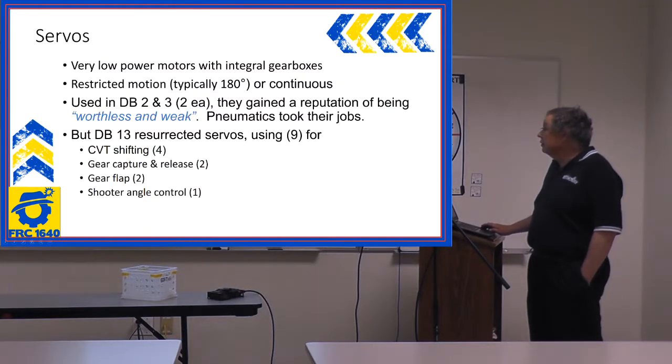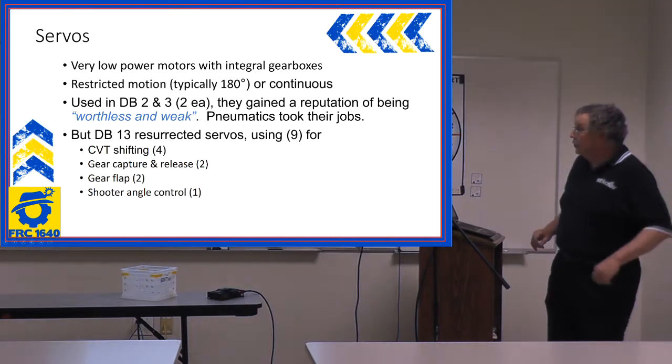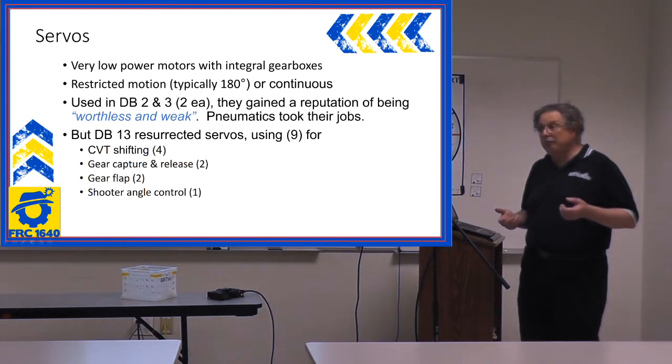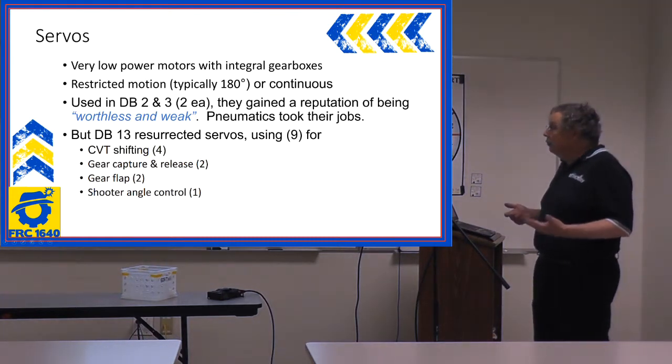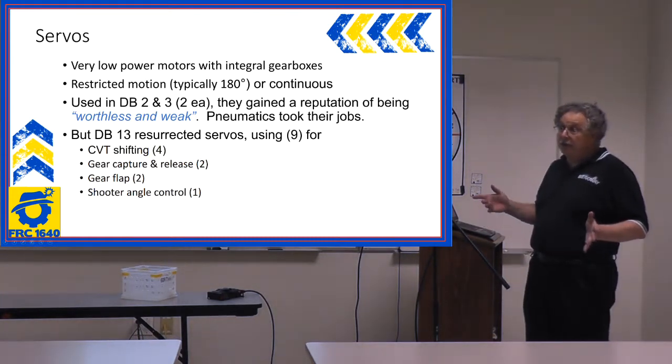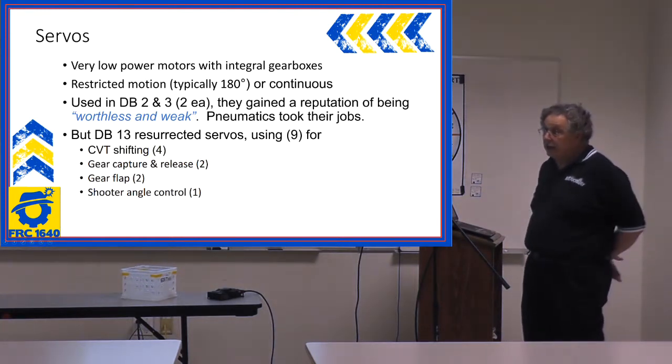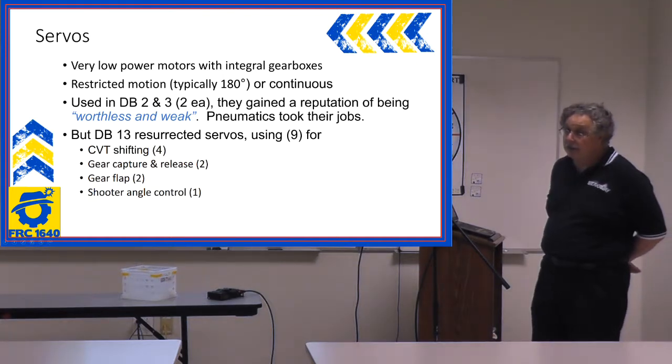So, servos. Servos are very low power motors. They have gearboxes built into them. Mostly they're restricted motion. Some of them do continuous turning, but a lot of them turn either 90 or 180 degrees.